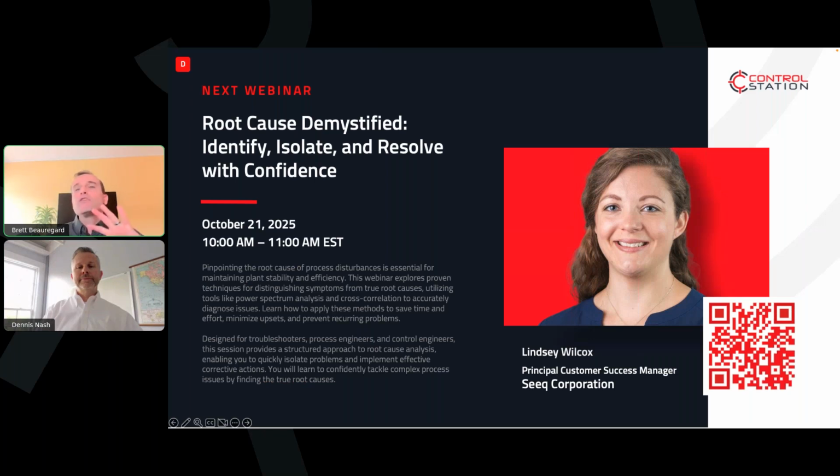But even just more so, if your controller is more aggressive than it needs to be, you are just going to have more full strokes. The actuator is rated for a certain number of full strokes, and it will need to be replaced sooner just because of that. That would be my answer to that one.